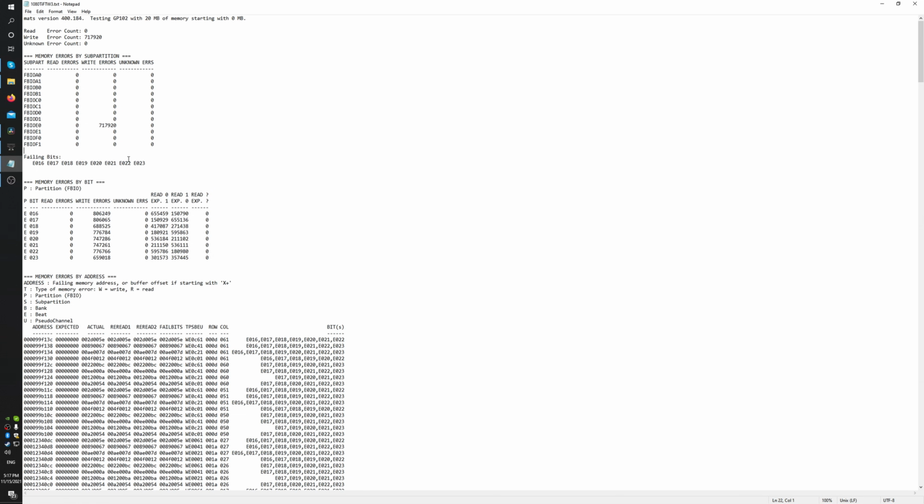So anyways, this card, as you may remember, has two distinct symptoms. The first of which is that it takes about a minute to post if used as a primary card. Unfortunately, I didn't show this. I kind of regret not showing this. But like I said, it takes about a minute to post, and when it posts, the backlight of the monitor turns on, but there's no image. The second hint is the fact that when it's used as a secondary card, it causes the system to become unstable and crash. I think you should have seen the blue screen.